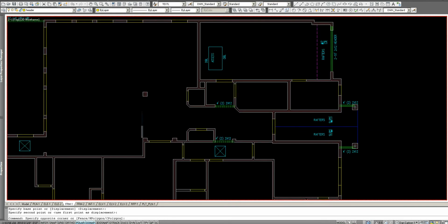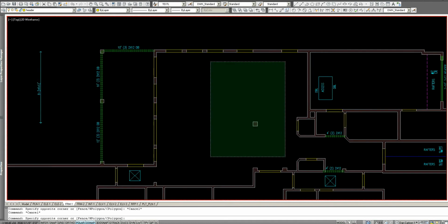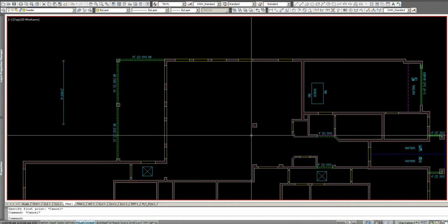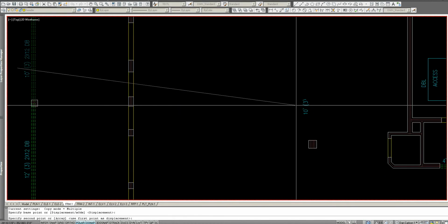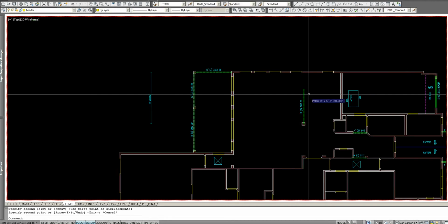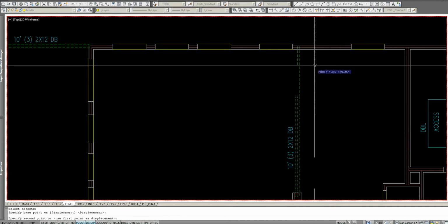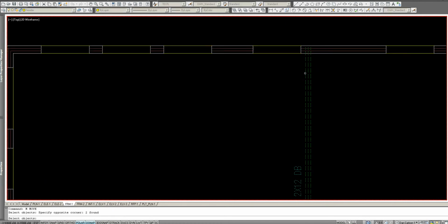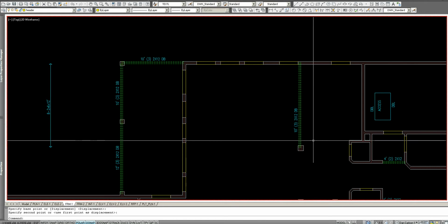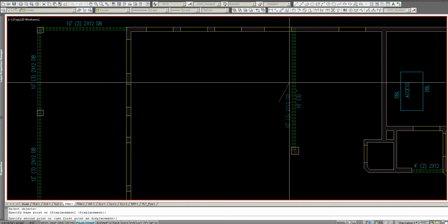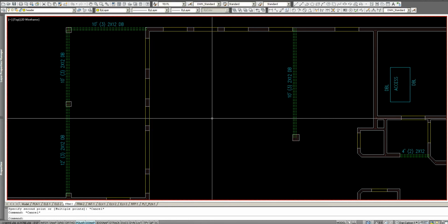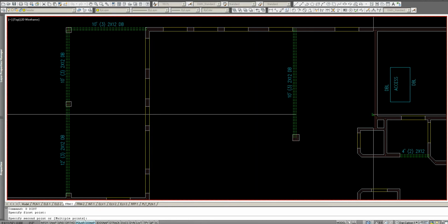We're going to need some beams in here. This is a big open room. We can't have our joists spanning this whole distance. So what we're going to do is put a beam here. And as much as possible, we don't want this beam on top of this window. So sometimes you can't avoid it, but in this case we can, and we have. So this is a span on the left of 18'1", and a span on the right of 9'8".